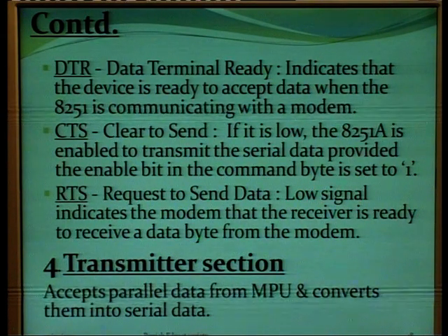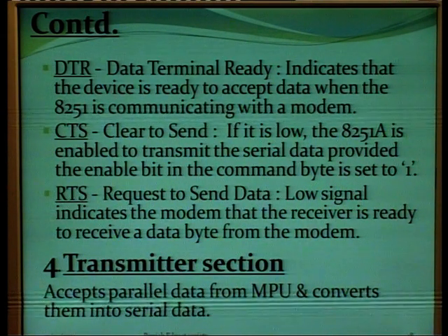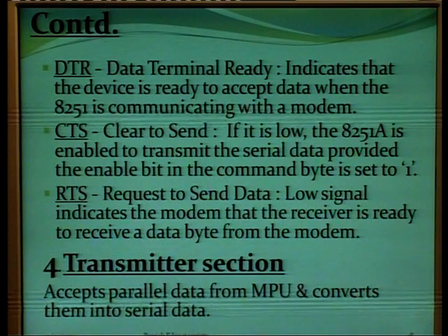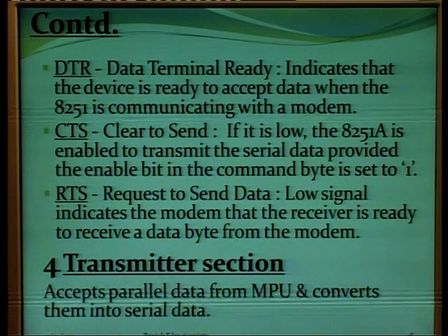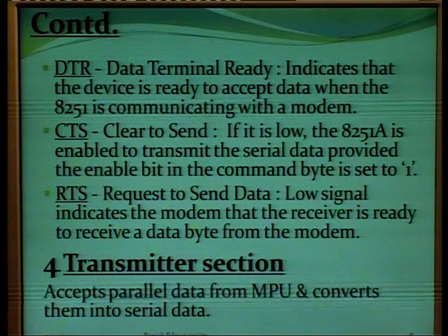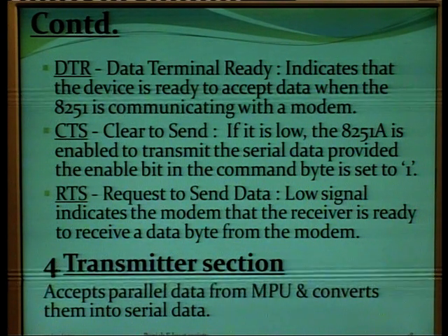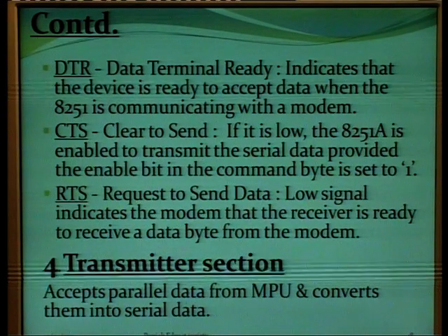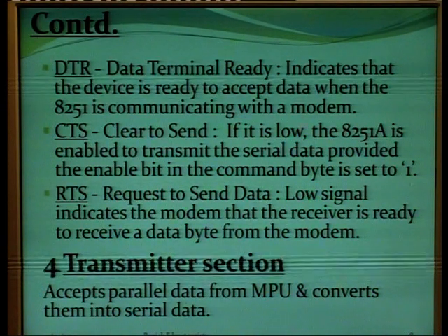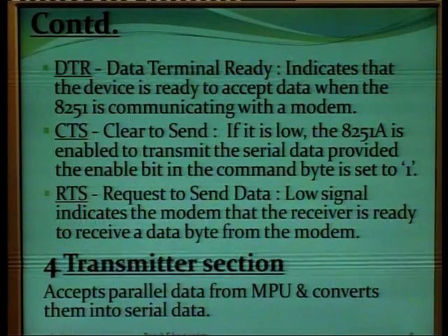CTS, clear to send, indicates that 8251 is able to transmit the serial data. RTS, request to send data, low on this pin indicates to the modem that the receiver is ready to receive a data byte from the modem. Then the fourth section is the transmitter section.